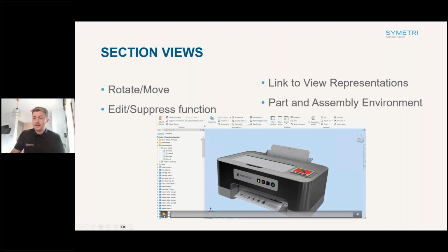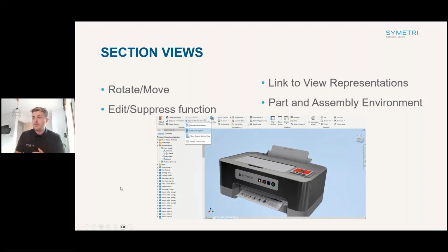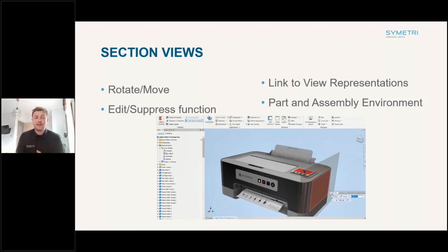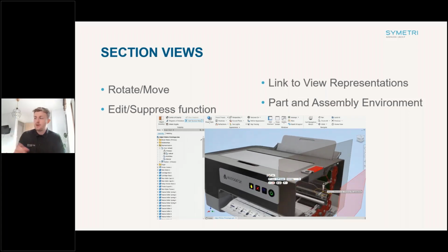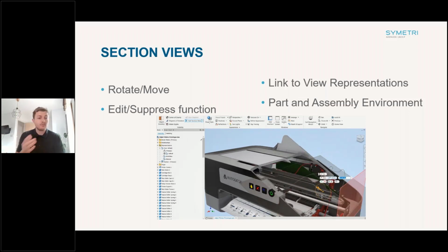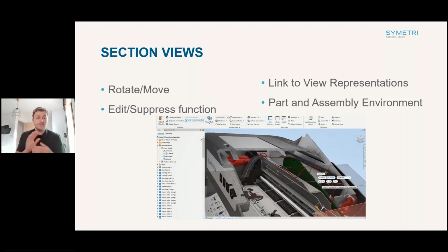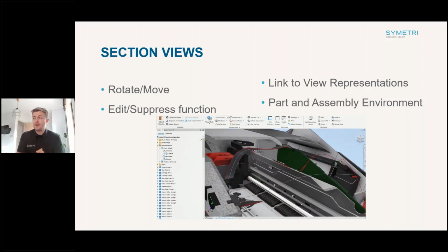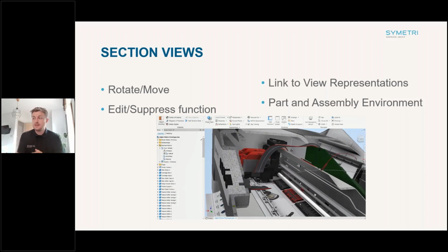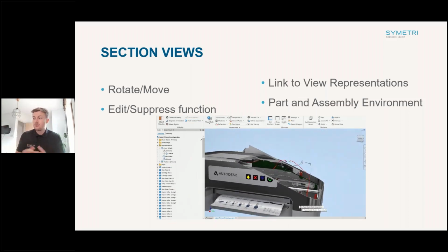So what I'm going to do is play this short clip. We're going to create a half section view within there. As normal, you can create your half section views by selecting a face and moving it. What you'll notice is you've now got a little sub menu where you can rotate the plane based off of the plane that you've pushed it in off of, and it will use the UCS to rotate around a specific angle of your choosing. So you can now create more custom and niche angles. I'm just going to pause it there for a second.